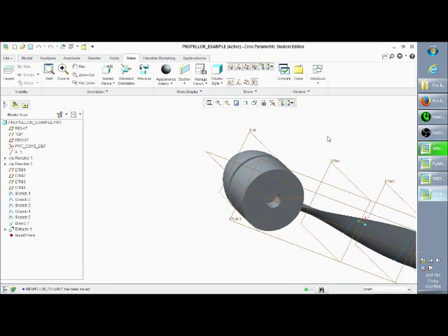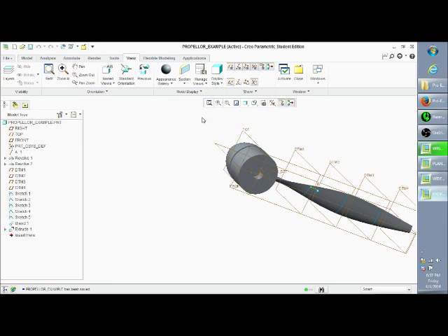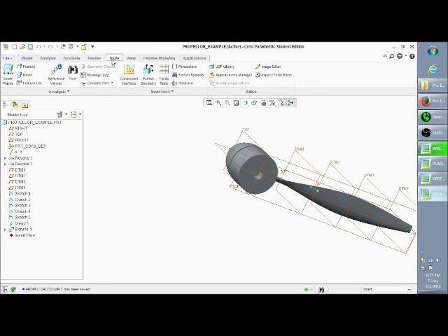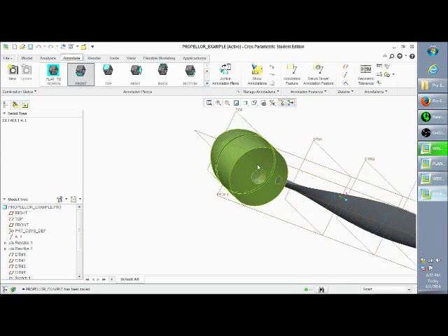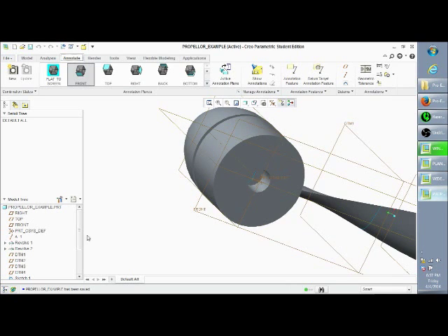So just make sure. What I want to do is create an extrude for the nuts that rests on, or comes out of, this surface. I created this circle earlier. If you want the dimensions for that one, it's a diameter. It's using an extrude cut going in. The diameter is 25, and it's going in by a depth of 20.